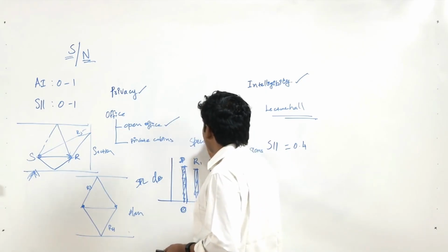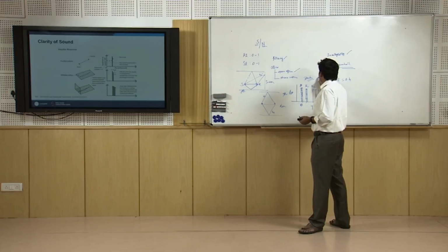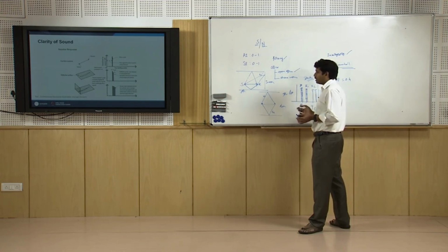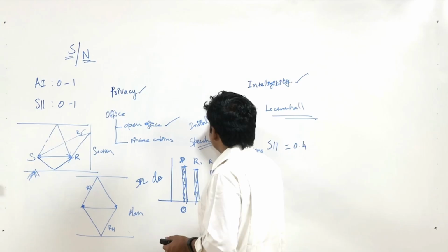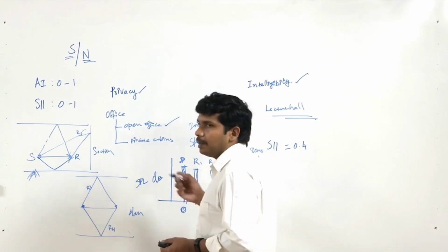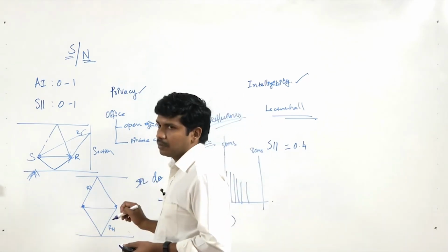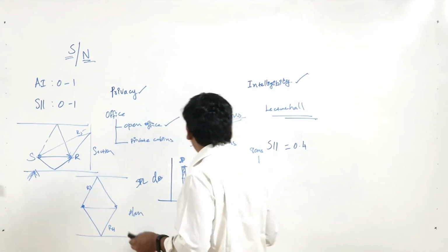When somebody is talking, say in a classroom or a lecture hall, you take a threshold of 50 milliseconds, which is really useful reflection. Like I said earlier, some reverberation is needed. These are called initial reflections. Initial reflections are useful. These reflections will in fact help reinforce the original sound, so the direct sound does not seem like a very dry phenomenon.